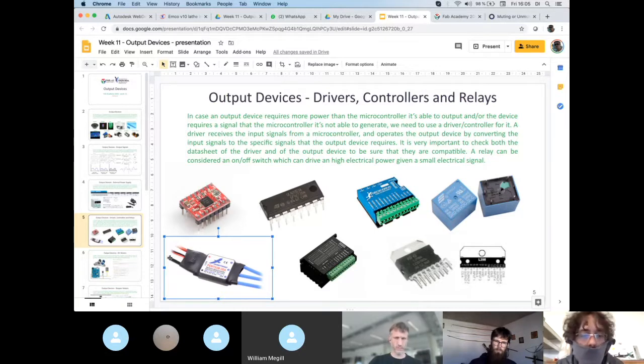So you have these 2 big cables, like this black and red cable, that are coming from the power, and then you have this white, red, and black cable over here, where one is for the pulse width modulation signal, the ground is to share the ground, and this red one is, in some electronic speed controllers or ESCs, a step-down voltage regulator.